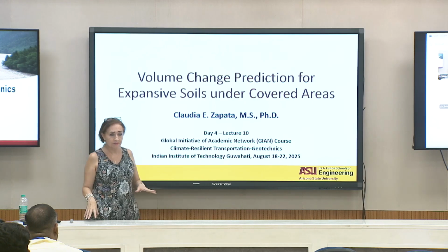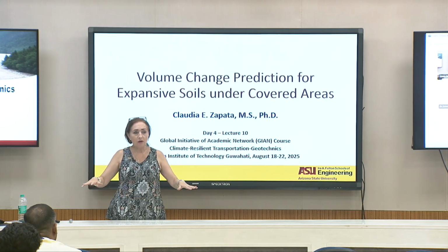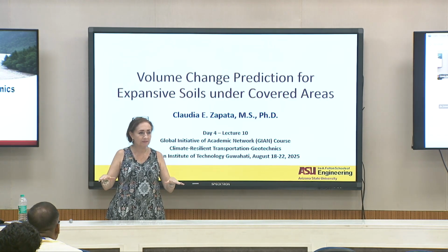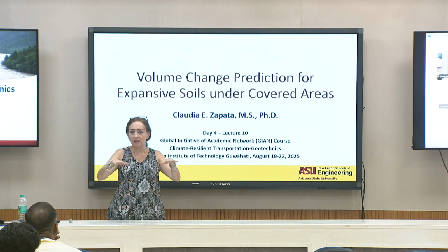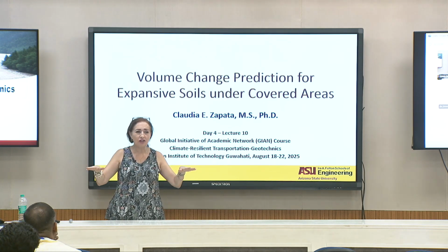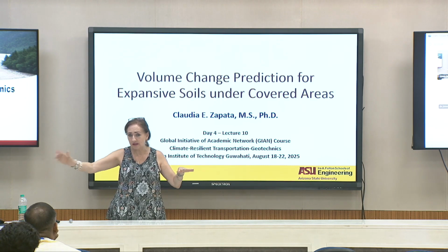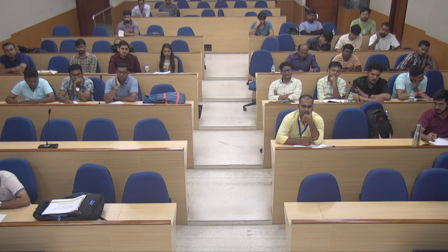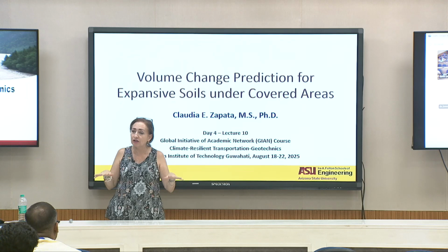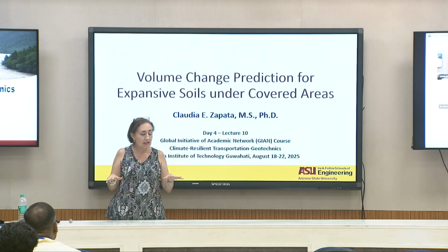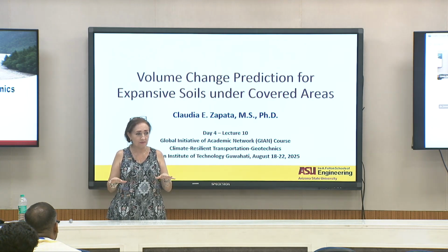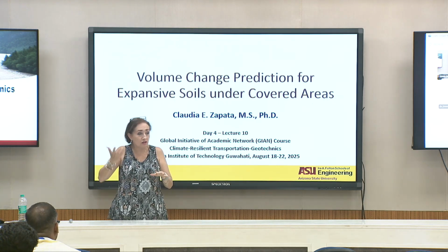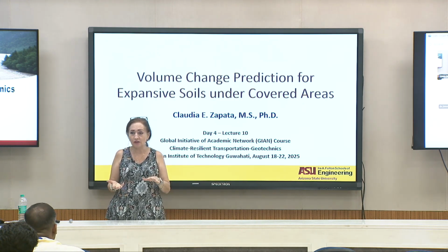If you have a road, the road has some overburden pressure on top, right? It has the granular material and the asphalt layers, and that doesn't change much during the year of the pavement. Add a little bit of surface layer or something, but actually the net normal stress, the static load applied to a pavement structure, is usually kept constant, correct? So any changes in volume due to the expansive soils will be due to the changes in suction, the stress of the suction, okay?